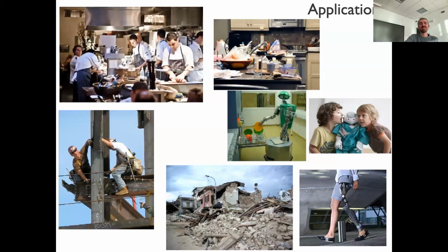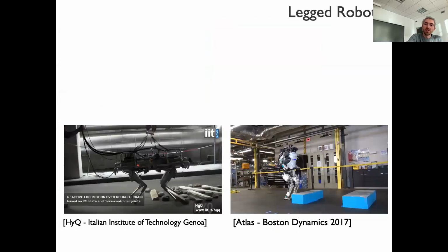But may I ask, what is the difference between the models from the 80s up to today? What's changed? I mean, you saw some quadruped robot back there. It depends on the kind of robots. So quadrupeds have mainly evolved in the direction I just described: using bigger motors, which allows you to have smaller gear ratios because the motor has more torque.